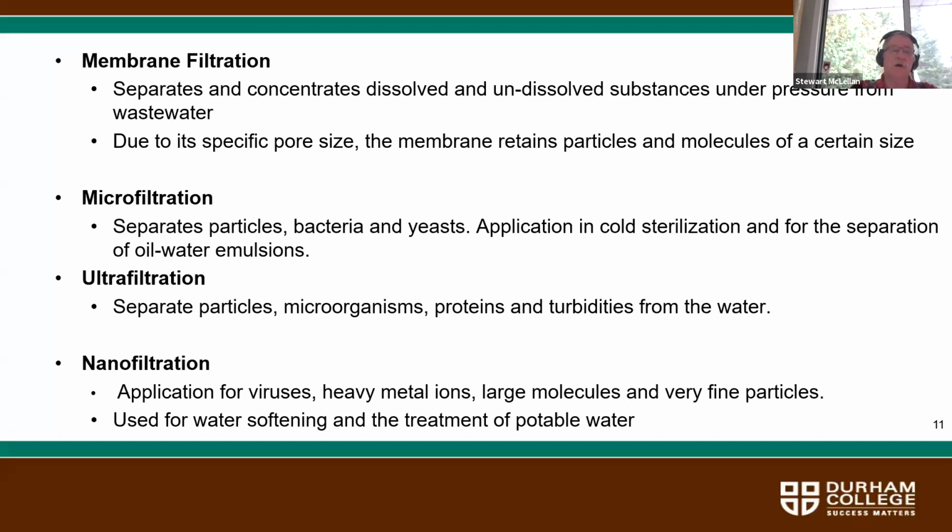Microfiltration systems are out there for the removal of these oil-water emulsions from water prior to discharge, and we see them commonly in industrial facilities that generate large amounts of oily water. Part of the problem in industrial facilities when they generate these oily water wastes is it's usually being pumped, and it's usually passing through process equipment, which tends to agitate the oil-water mix, which in turn results in emulsions. And once those emulsions are formed, they are very difficult to remove from your wastewater.